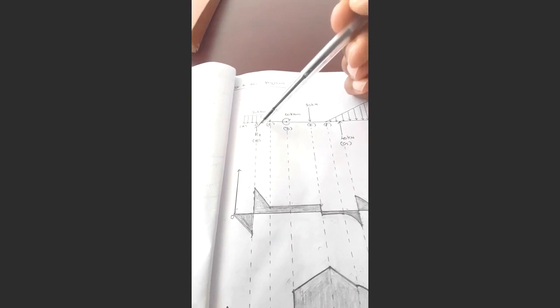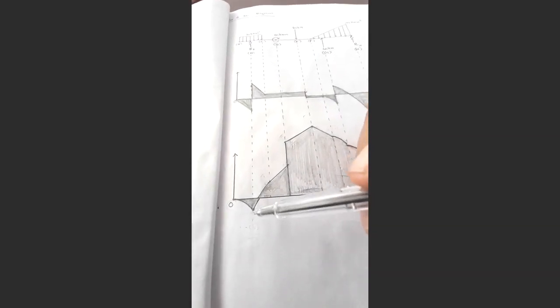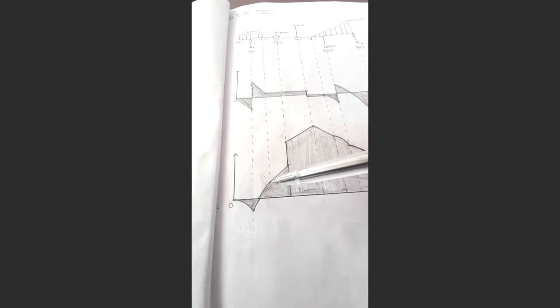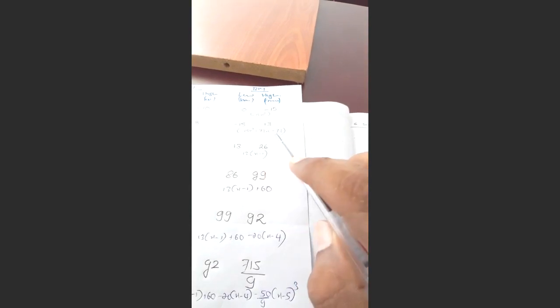And then for the next bending moment, the next section BC, we are going to sketch for section BC. For section BC, the lower limit bending moment is 13, higher limit is 26. First mark that: 13 lower limit, and upper limit 26, over here. This must be the same curve. Just look at the order. It is a second degree curve.